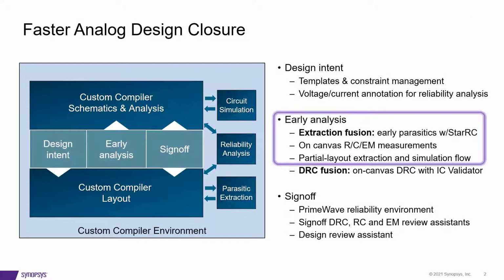In the first part, Denis highlighted the pre-layout parasitic estimation and planning. Designers can estimate resistance and capacitance from routing specifications or extract from partial layout using signoff RC engine, and then use PrimeWave Design Environment to easily control which parasitics are included for their pre-layout simulation.